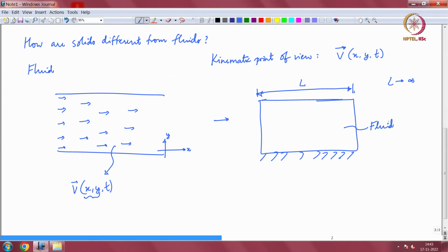If you want to get a flow in the fluid, there are usually two configurations that you have probably seen multiple times in the fluid mechanics course. The first is of course you can apply a gradient in the pressure in the x direction, again this is x, this is y, the origin of coordinates does not matter. So, if the pressure here is P1, pressure here is P2 and you have P1 not equal to P2, then you can get the fluid to flow either left to right or right to left depending on which one is larger, right. So, you get a flow in response to a gradient in the pressure.